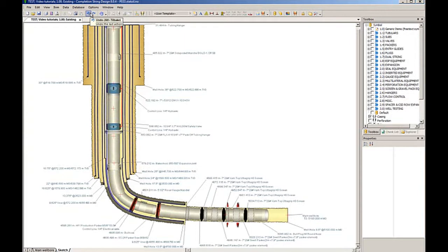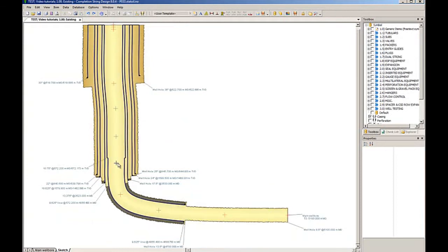If you want to move several control points at the same time, this can be done by holding the Control button down and selecting each point. Or you can hold the left mouse button while dragging the cursor over the control points you want to move. When you release the mouse button, the control points which are displayed inside the rectangle will be selected. The control points will now have a blue color. Then use the mouse pointer to drag the points to the position you want.